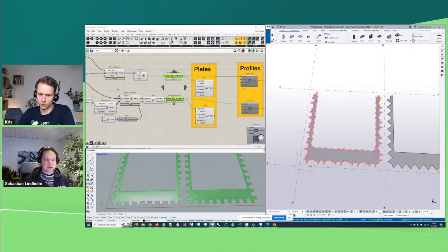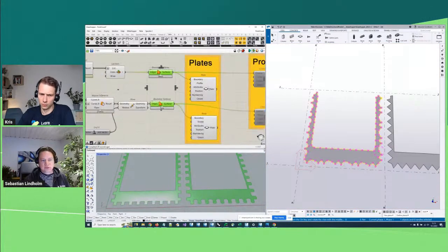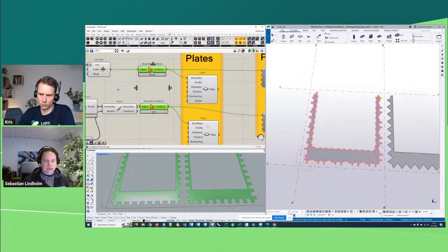And that's simply because when we transfer them to Tekla, we don't have enough control points to be able to represent them accurately. So the default number of control points that we have in Tekla is 100 maximum, or 99, I guess. And that's for historical reasons. Now in later Tekla versions, you can have up to 999 points. But that also means that the model can get a bit slower if you use a lot of profiles with a lot of control points.